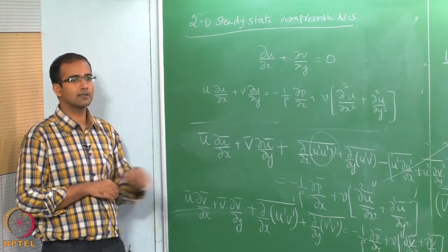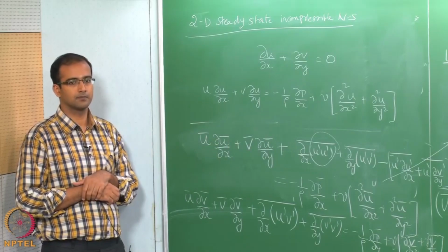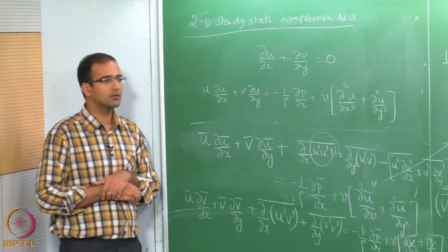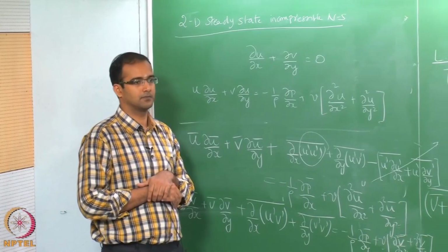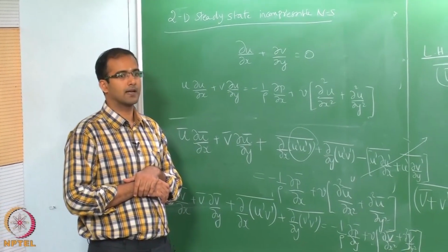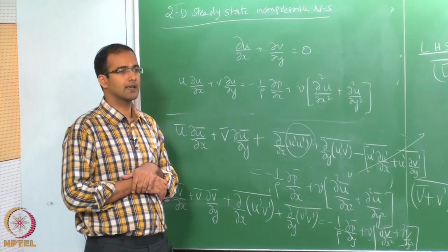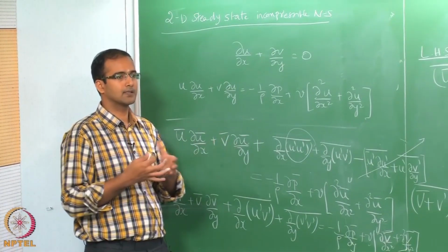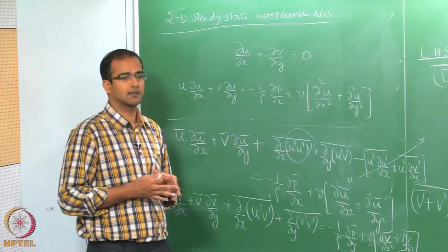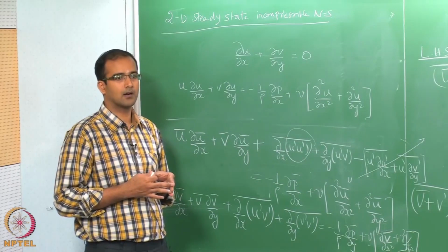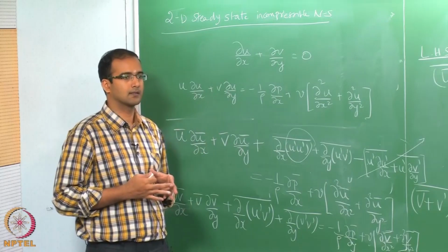These are now called turbulent stresses. Although the nature of these stresses originates from the advection term, they are named turbulent stresses just for the ease of grouping them together. They are grouped along with the viscous stresses and called together the total stress.